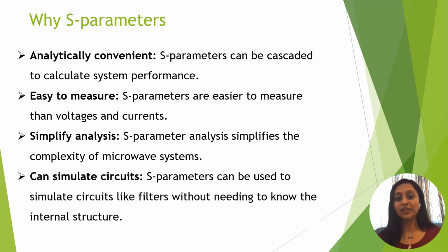Analysis also gets simplified if I am considering very complex microwave systems. And it can simulate circuits. S parameters are used to simulate circuits like filters, which need not have the internal structure. I don't have to know the internal structure of a filter to find out its S parameters. That makes me analyze the complete circuit with S parameters.